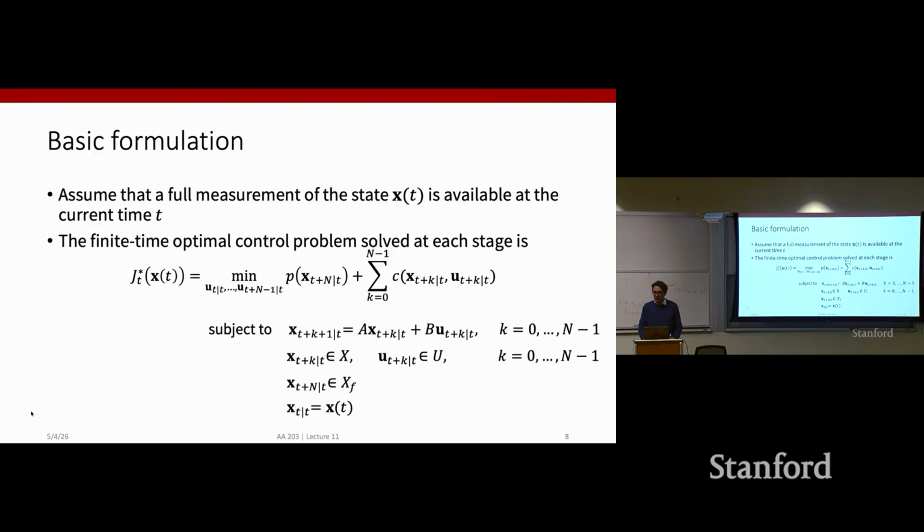Any questions here? So here what I want to highlight is these two guys. These two guys are additional terms that we inject in our MPC formulation to regularize it. You know, our optimal control formulation basically has the running cost, has the control constraints.